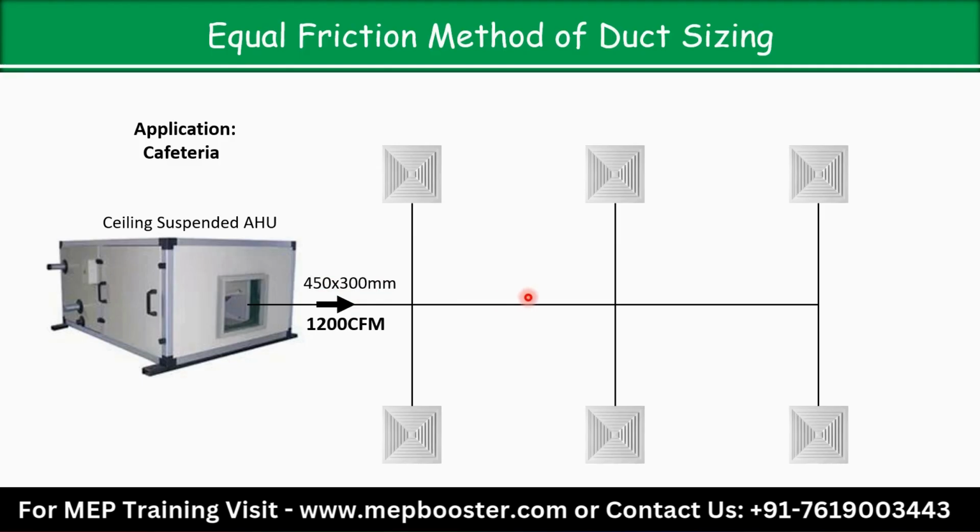When you are doing the sizing, remember, for the main duct always try to maintain the height constant. Suppose in the starting you have taken the duct height 300, so always try to maintain the height for the main duct at 300 only. So let's say for 1200 CFM we have got the size from McQuay, 450 by 300.